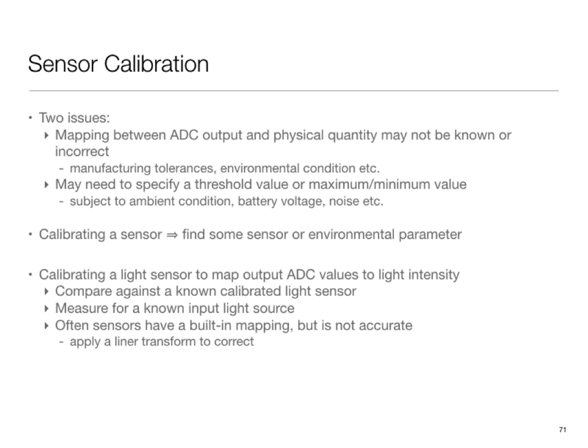For example, on your phones, you may have noticed that the magnetometer often goes out of calibration. Any of you encounter this thing where it says move your phone in a figure 8? The reason that happens is that with the technology these phones use, the sensor has a persistent change when it is exposed to large magnetic fields. So over time, the sensor's baseline changes, and you are still okay for certain tasks where the change in value is what matters.